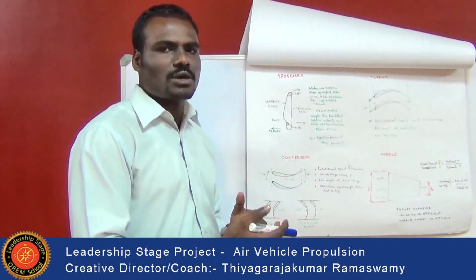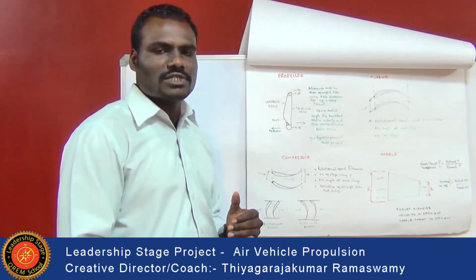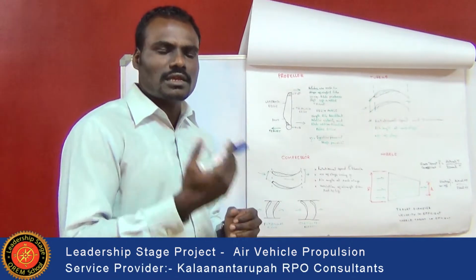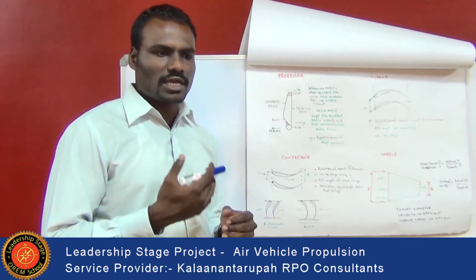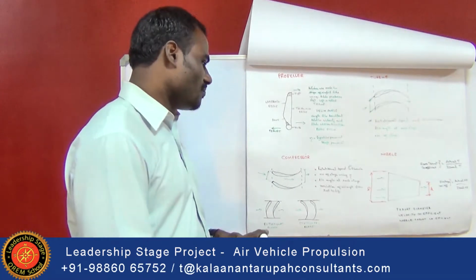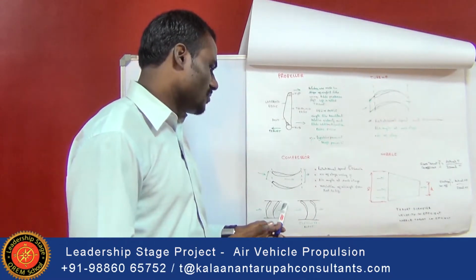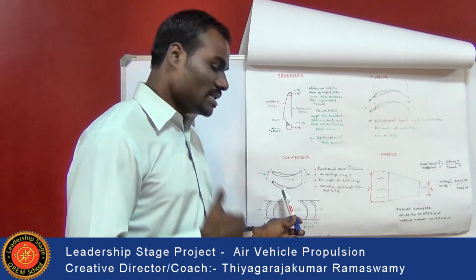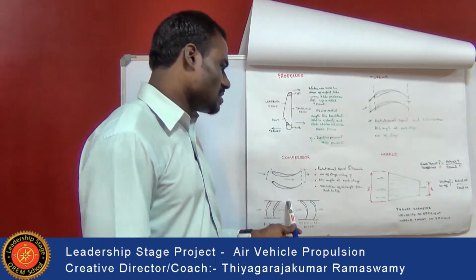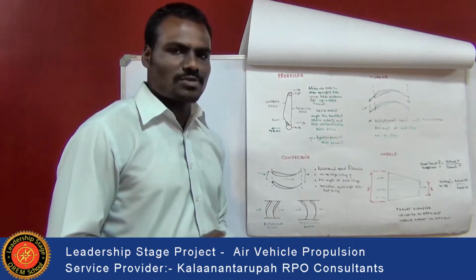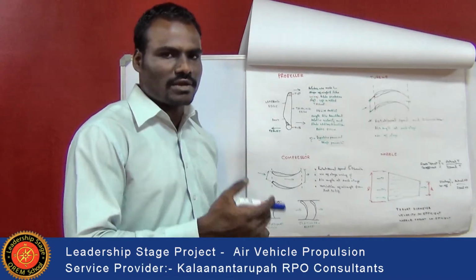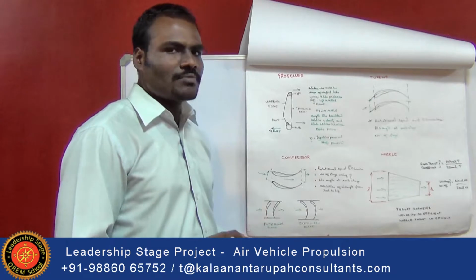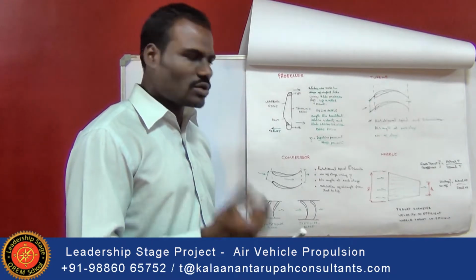The number of stages depends upon the aircraft being used, and based upon the power of the aircraft, the stages will be increased. The major factors to be considered are the air angle at each stage, and how the variation of the angle is to be carried out with respect to the tip of the blade and with respect to the root of the blade.